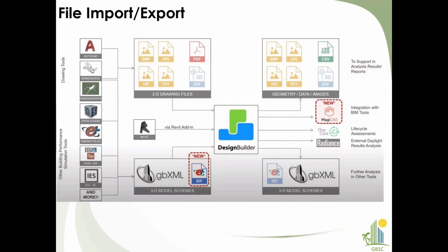So for the geometry part, we don't have to spend much time on the modeling front. Similarly, if we have a PDF file and don't have a CAD file, we can import the PDF file, scale it down, and then trace the geometry. We can even import CAD files, image files, and files from Rhinoceros using gbXML format. These are the input interfaces which DesignBuilder supports.